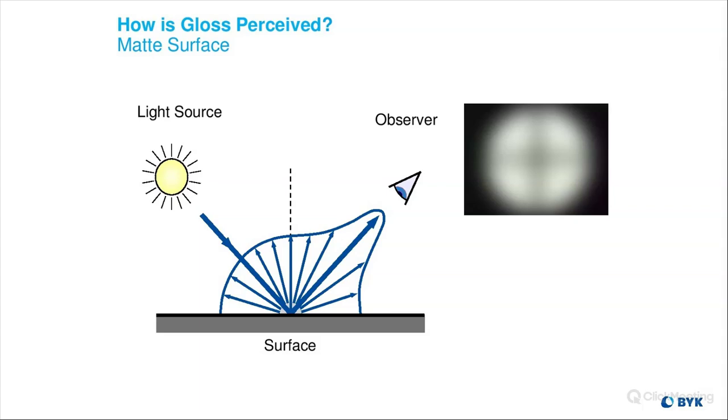Adding too much film build might create some sort of haziness on the top coat, some sort of solvent pop that's going to create a haze in the clear coat. So it can affect it. Again, it's going to depend on your application and what your standard for mil thickness is. So exceeding that mil thickness may have an effect on your gloss. Okay, good.